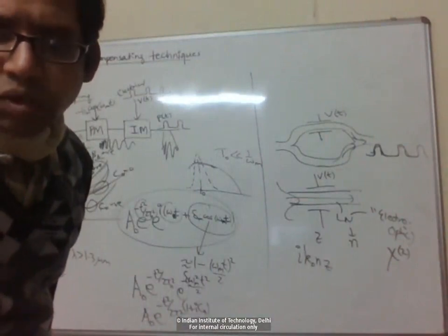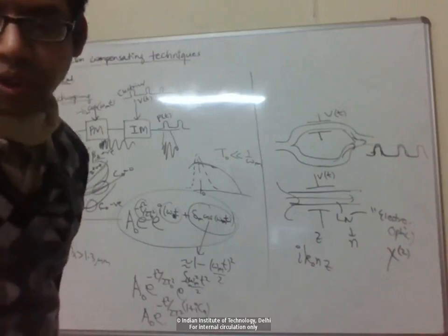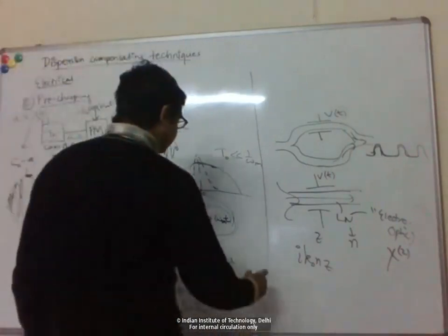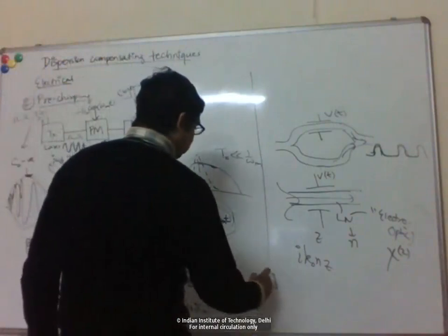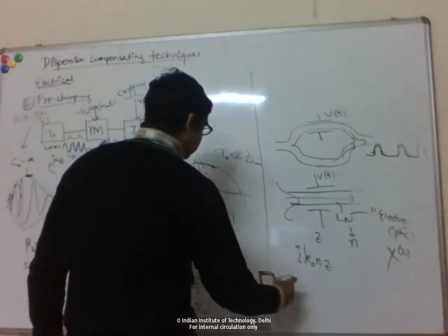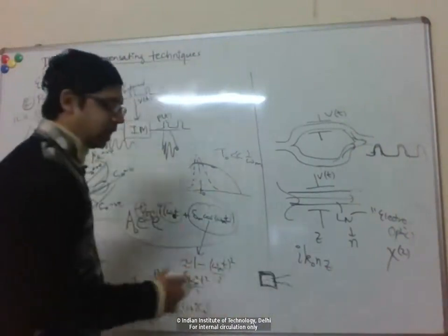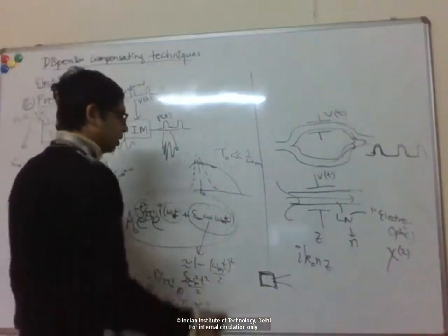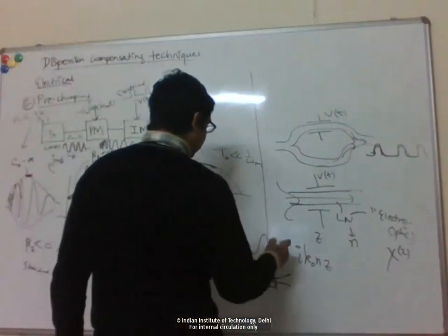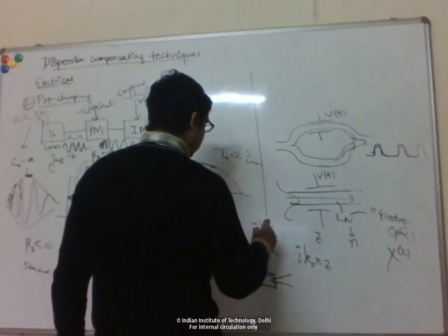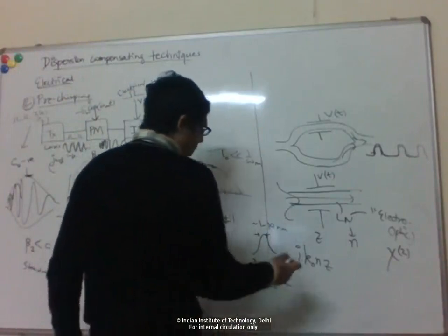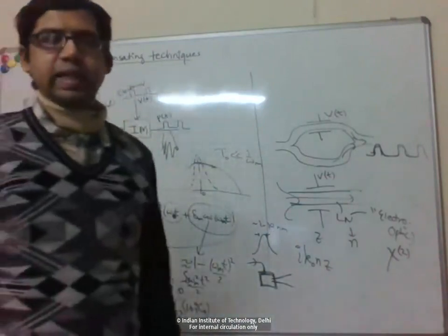Question is, can we modulate current for a non-coherent laser source also? Yes, you can. You can use what are known as laser diodes. They are just some p-n junction device, intermediate between an LED and a fully stabilized laser. They have broad bandwidths, typically 1 to 10 nanometers. And so yes, you can current modulate lasers, and you can also current modulate LEDs.